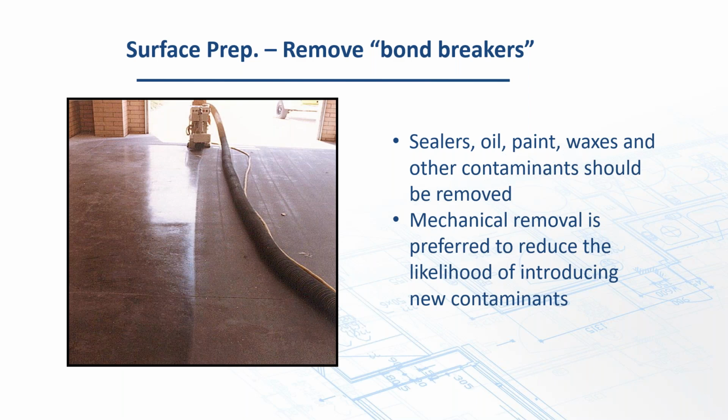Mechanical removal is always the preferred method. We do not recommend that you go in there with chemicals and break it down. That just penetrates the slab further. So now all of a sudden you might have to remove, instead of what's just on the very top surface, maybe you've allowed it to penetrate as much as 1/8 of an inch.